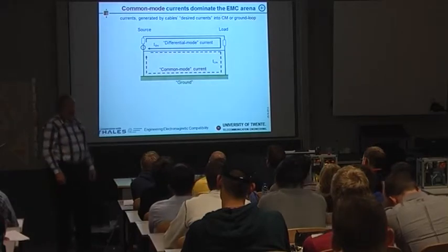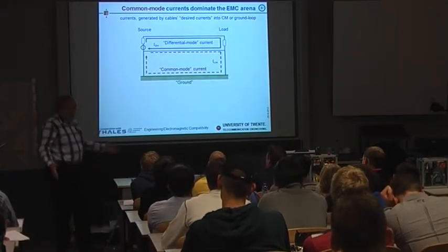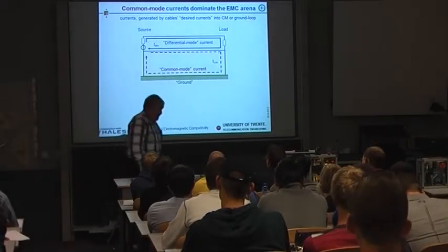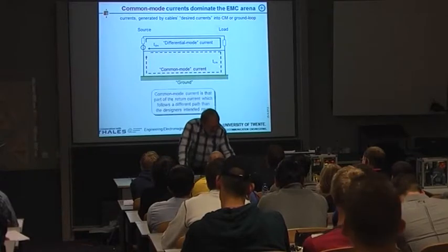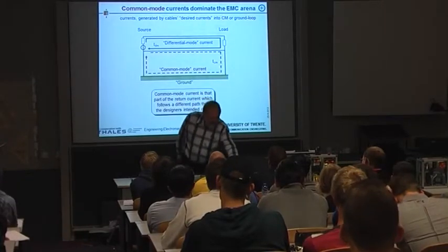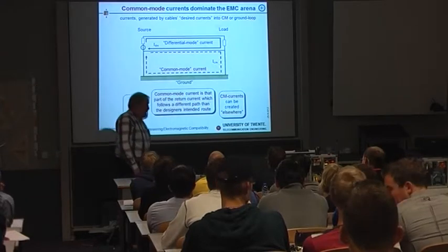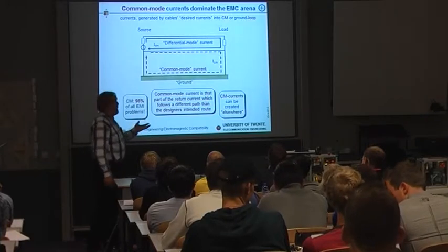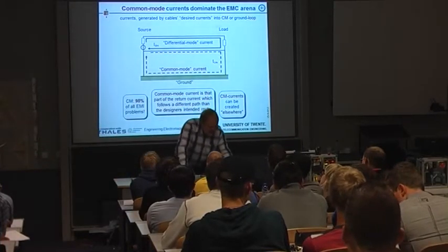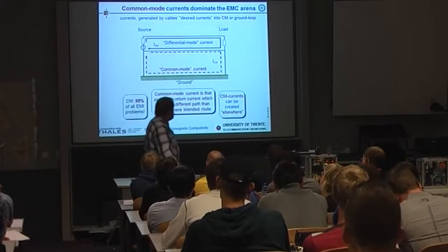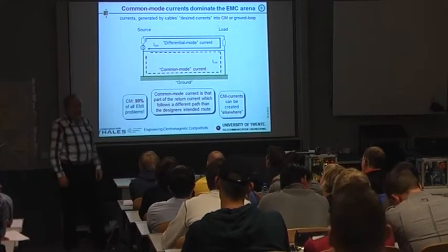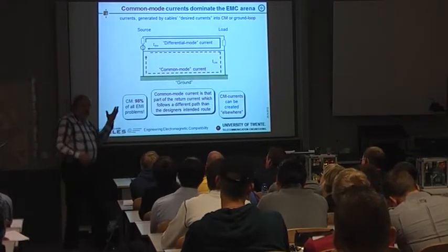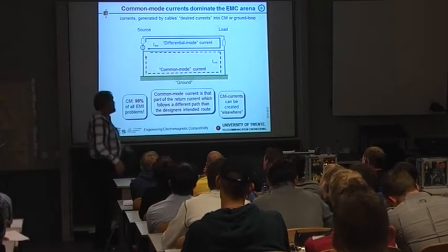And so you see common mode current also flows in loops. It's a current, it doesn't know it's common or differential, so it flows in loops. All currents do that. That's a definition. Somebody else could make them. That means it could be a neighbor generating the common mode current, and you would have the current. And then you would probably have an immunity problem if there's any interference. And then 98% of the EMI problems is common mode, maybe even 99. So if there's an EMI problem, start with the common mode, differential mode comes later.